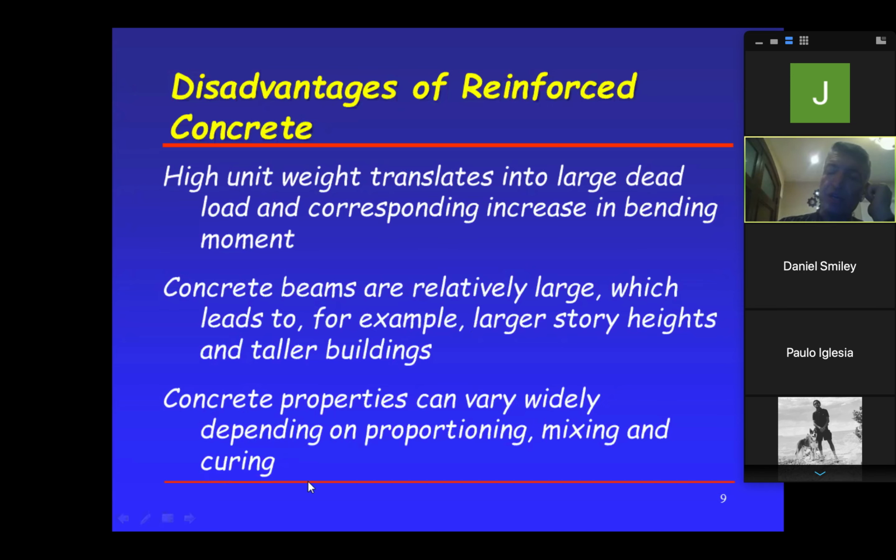And also you can cure by spraying some chemicals on it. We call it chemical compounds, chemical curing compounds. When you do that, you will see that the concrete gets a color, but then ultimately that color goes away. So there's many ways, but the quickest, fastest, and easiest way is to just dump some water on it. Again, curing is a very important term.